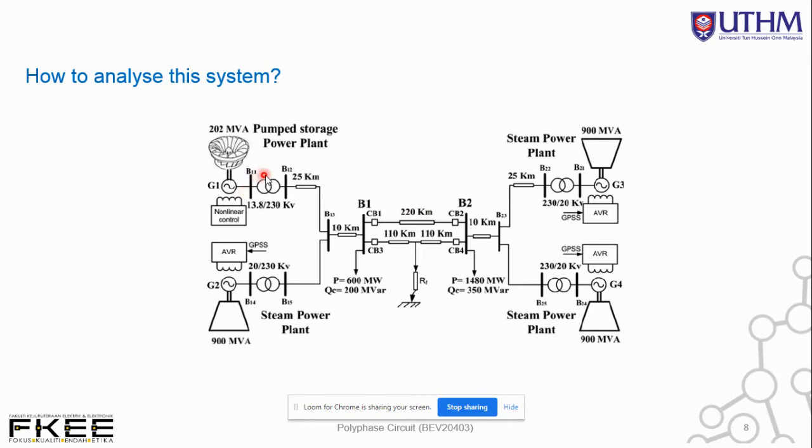You can see the bus bar connected from the generation part to the transformer part, or step up transformer, for example. Then we have another bus bar for the connections before it goes to 25 km distance, another bus bar, 10 km distance, and finally to the consumer. So this tells you that even though the system is generated by multiple power plants, it can still be integrated and linked together. That is the brief idea of how it works.